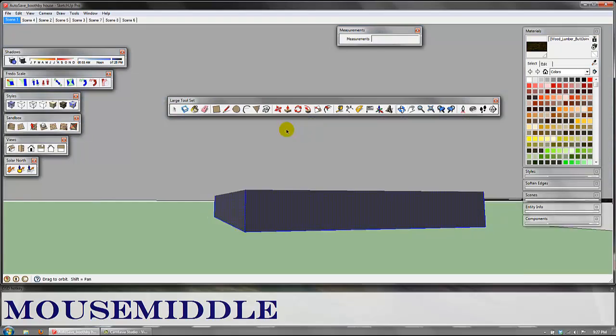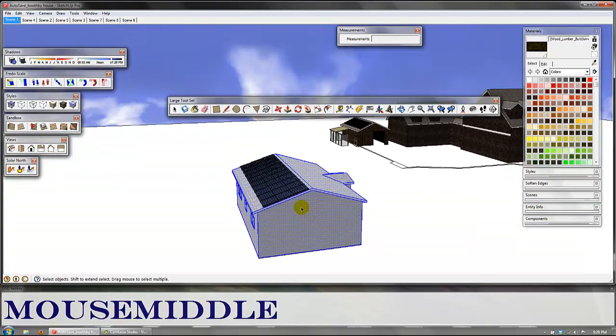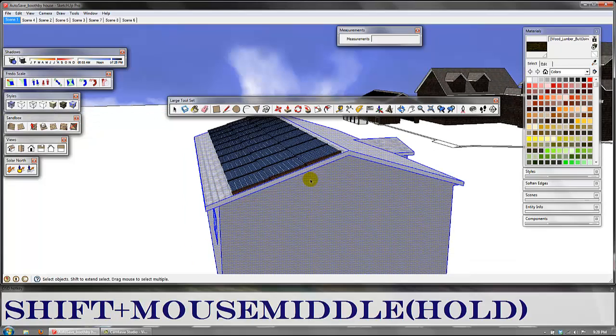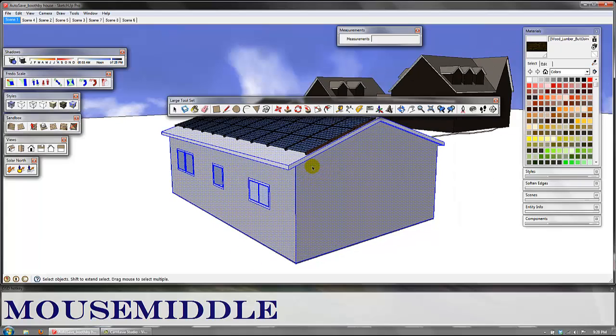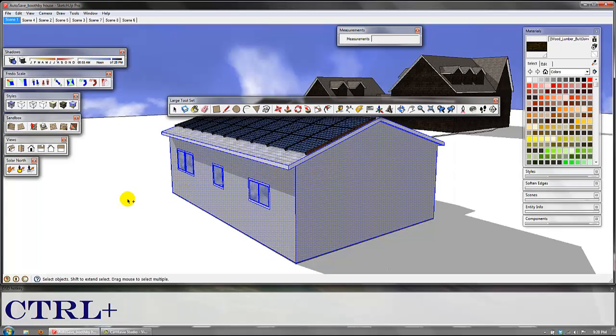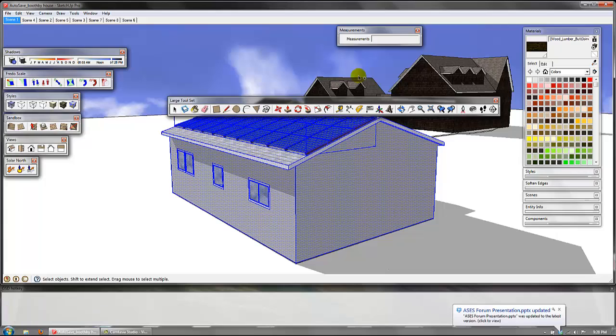And in this case, this whole house is ungrouped. So that's why it's all selected and this is not. A couple other things before I move on. If I'm holding Control with the Select tool, you see the little plus sign now by my cursor on my arrow. That means whatever I select now will be grouping. Not grouping, excuse me. I'll also be adding selections to the selection I've made.